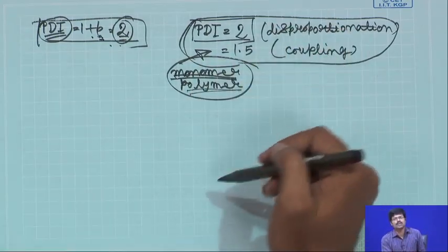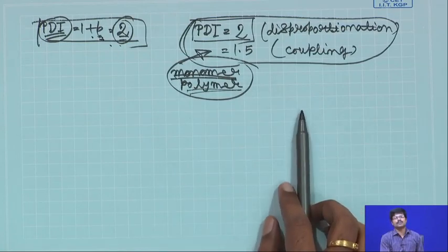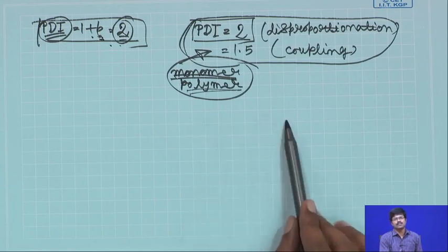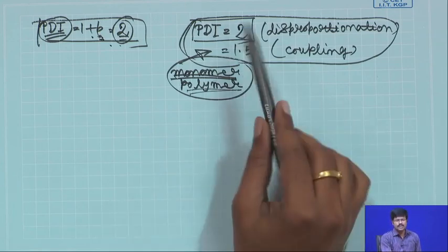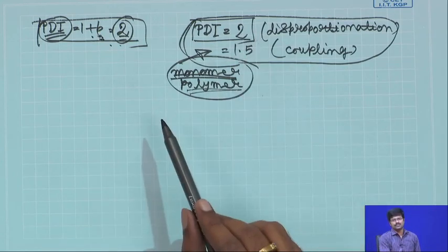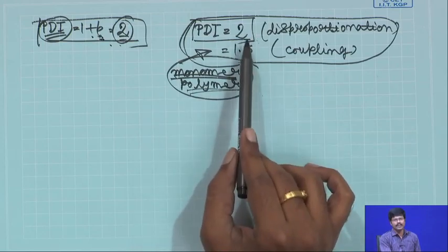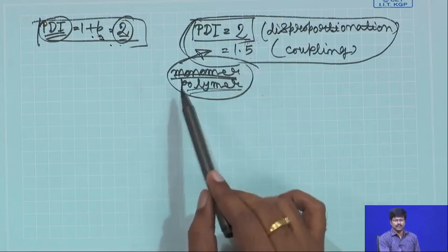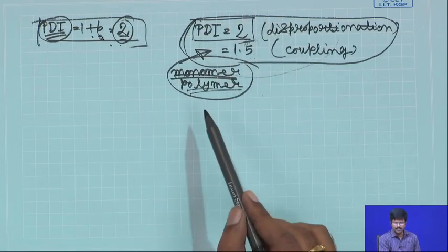But this kind of situation cannot be realized in a batch reactor, because the monomer concentration and polymer concentration are not the same as a function of time, they are changing. So, these are unattainable limits for a batch reactor. You will get in practice much higher PDI in a batch reactor if you are doing a radical polymerization. So, this is the limit for radical polymerization.